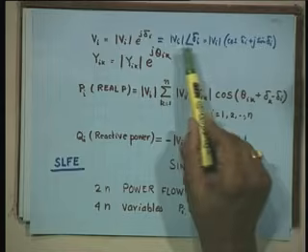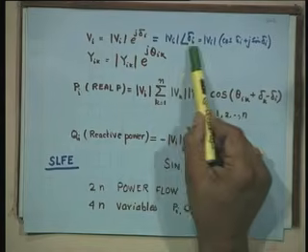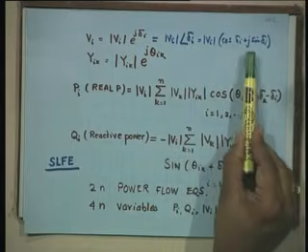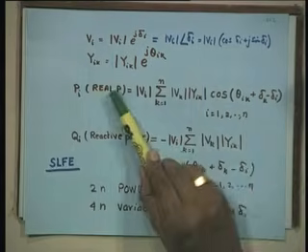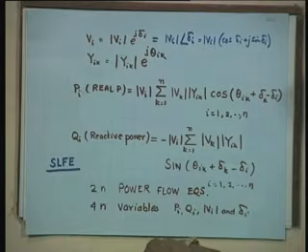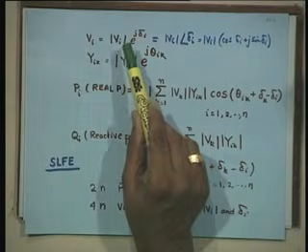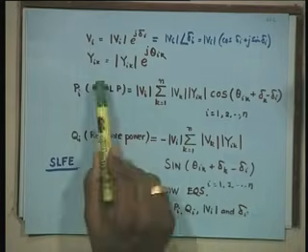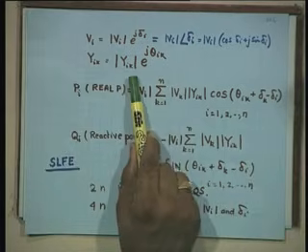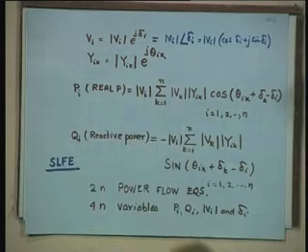So, we have put it as an amplitude or magnitude, and delta_i becomes the angle here in polar form. The same thing if you expand it, cosine delta_i plus j sin delta_i times |V_i|, becomes the rectangular form, A_i plus j B_i, and this is the angular form, and this is your exponential form. Similarly, y_ik, which is the admittance between the nodes i and k, can be expressed as a magnitude and an angle; the angle is theta_ik.